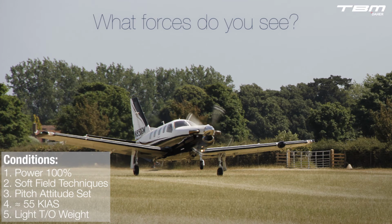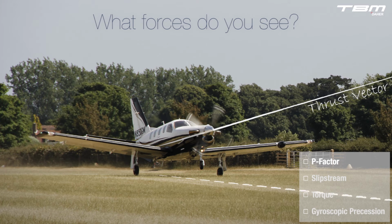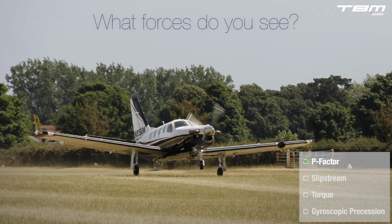Since the aircraft is light, with a high power setting, at a low airspeed, the optimum conditions exist for the propeller's effects on the airframe. Can you visualize the angle between the thrust vector and the flight path? In this example, the flight path is the ground run. With power at 100%, the left turning tendency resulting from P factor is at a maximum. With maximum power and minimum aerodynamic control due to the low airspeed, a strong slipstream is curving around the fuselage and impacting the side of the tail, inducing a left turning tendency.